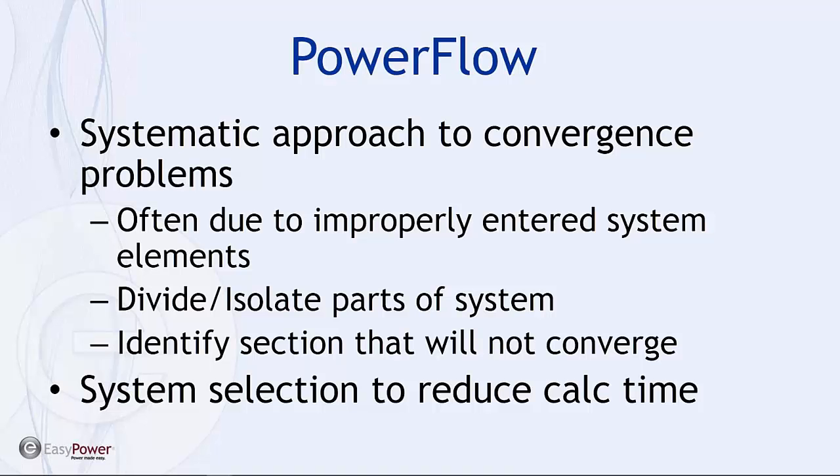Very frequently we'll take power readings, voltage and current readings when there's panel meters available, and then as we get the model developed, run a PowerFlow and see how close the PowerFlow results come to the actual parameters that have been logged, and that in and of itself will help identify system elements that were improperly set up.